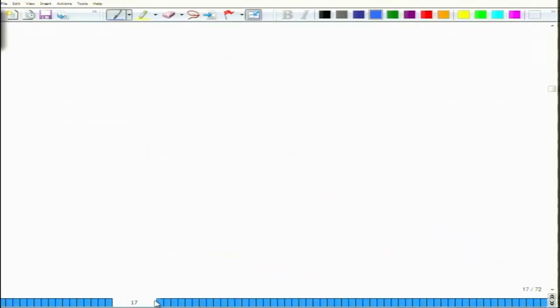Okay. Now instead of a coupler, we might elect to use what is called a circulator. A circulator is a very interesting device. What it does is, it has 3 ports. We will talk more about all these devices; I am just giving you an overall idea of the different WDM components that we use. So this is port 1, port 2, port 3, and the working of this circulator depends on the direction of the arrow. The arrow goes from 1 to 2, and then it continues in this manner, so it goes from 2 to 3.